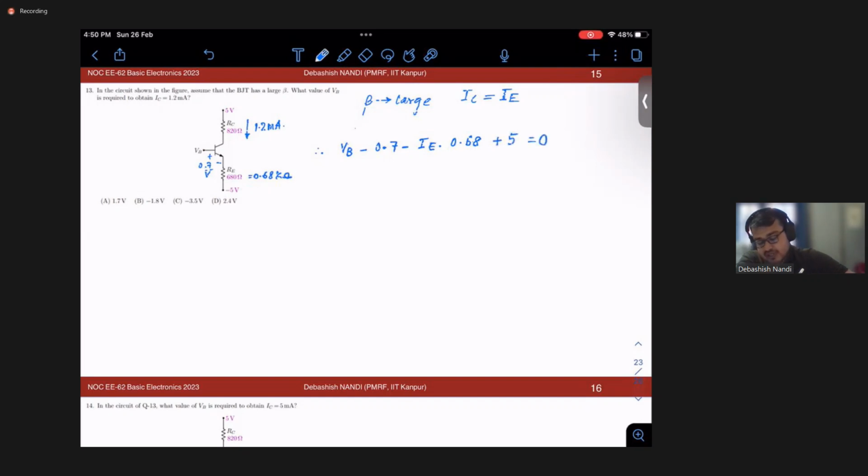It is not grounded. Note that there is some negative potential. This is generally the preferred way to bias a circuit. Instead of, let's say, a 10 volt supply at the collector, you can distribute it to 5 volt at the collector and minus 5 volt at the emitter, right? There are some distinct advantages for doing this. This we'll discuss later if time permits.